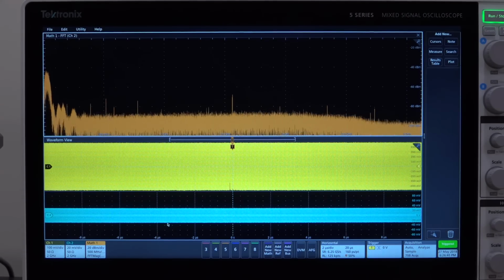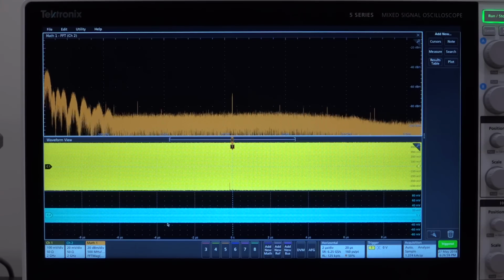And look at how much frequency content has been removed from the high frequencies because I've changed the rise time to 8 nanosecond. But this also tells me that I probably don't need to push it so hard. Even at 3 nanosecond, I already have a significant improvement. So here's 3 nanosecond, here's 2, here's 1. So just by reducing the rise time a little bit, I can save a lot of high frequency content from the adjacent crosstalk channel. And this already tells me I don't need to compromise on my eye diagram too much.